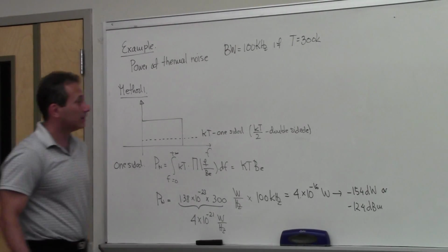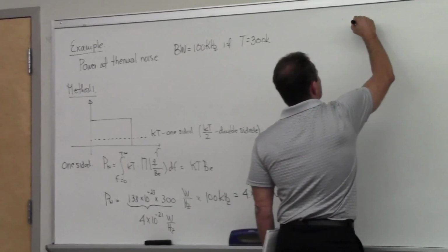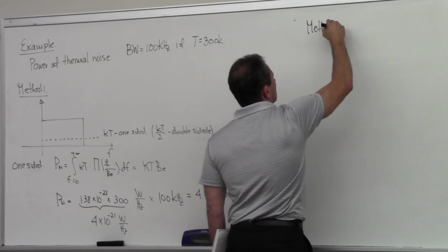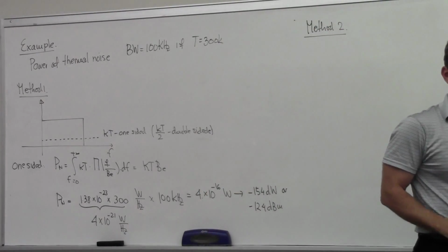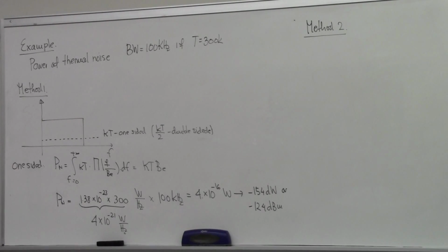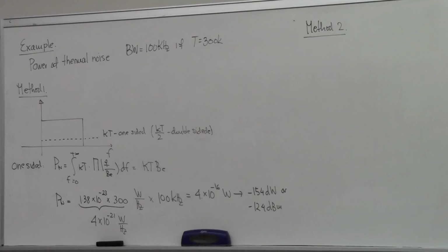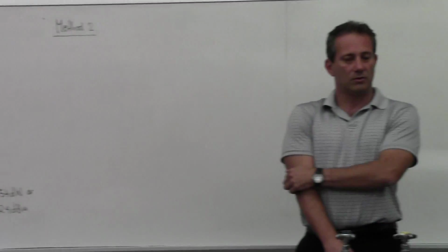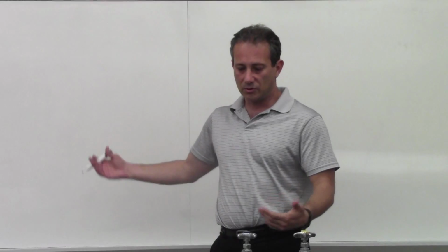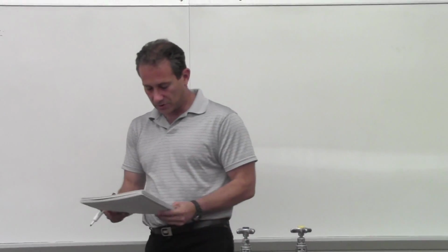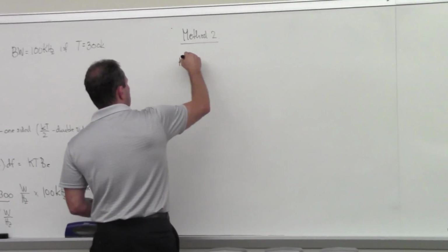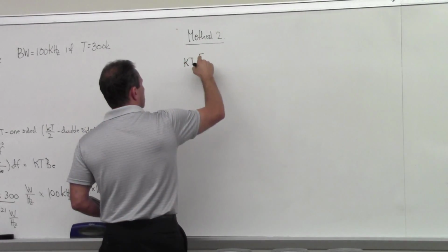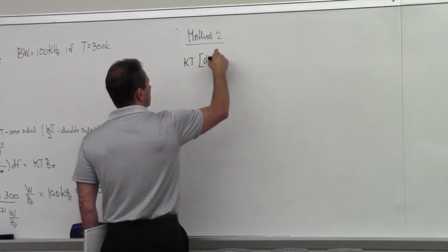If you talk to satellite people, though, here's how they approach this problem. I'm telling you this because it's not going to matter much in this course. You can do it either way, but if you start practicing, this is how they would be doing the link budget. First, they take this KT and express it in dB watts per hertz.